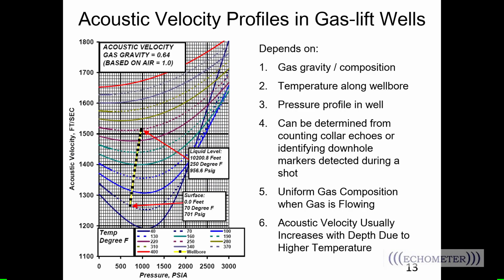And because the valves are so sensitive to temperature, someone probably designs it closer to the flowing one than the static one. So sometimes when we're troubleshooting and we've got gas that's circulating, we're really trying to establish an answer of, is there something wrong with that valve? And we can get that off the dual shot, right? We can find out if we've got gas coming around or not. But then the question becomes, if we could get the well flowing and get it to warm up, would that valve likely close? And that's the thing I'm trying to work my way through.